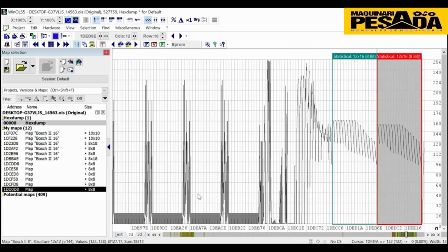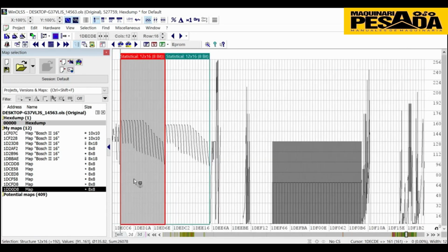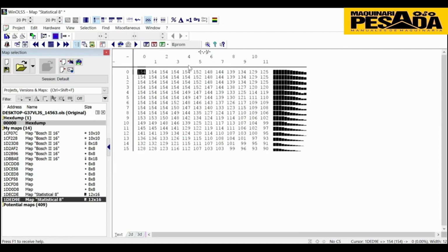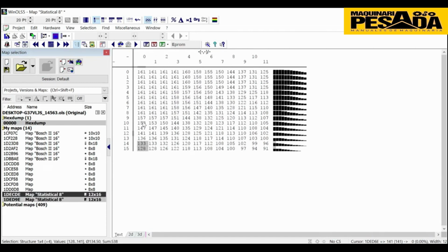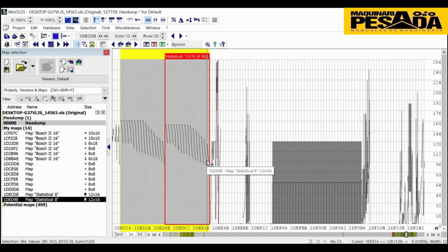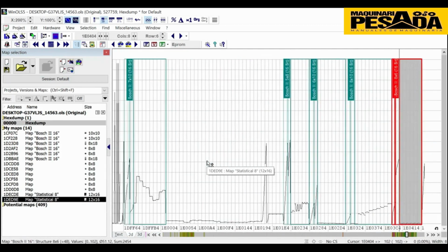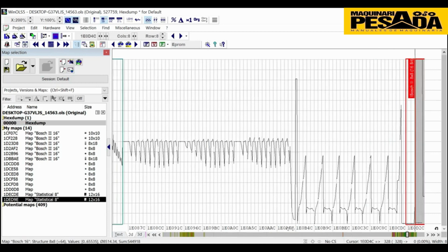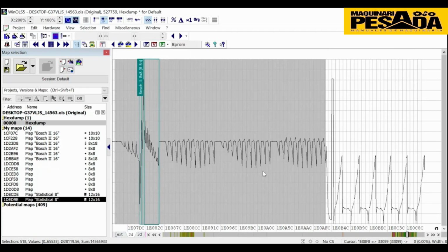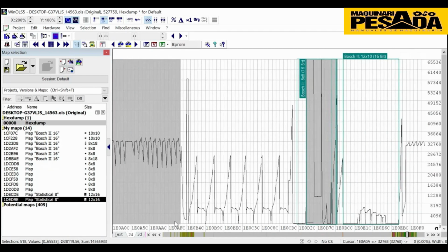And you need to make sure that you learn the 2D views and the maps. These are the lambda for component protection. In that specific car, the component values are more than 128, and it means that the manufacturer already asked for less fuel during the less working condition, less engine speed, less load. And look, these maps are for the turbo system, and I will have another session that explains it for stage 2 and 3 tuning.